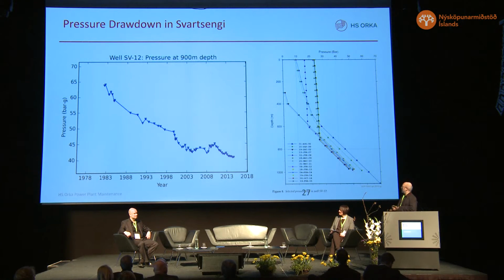We see actually the hill in the drawdown. It was because of a leak from an uncased part of our reinjection well. So we had an extra reinjection from the groundwater system into the geothermal system. But that was cased off and the problem solved.